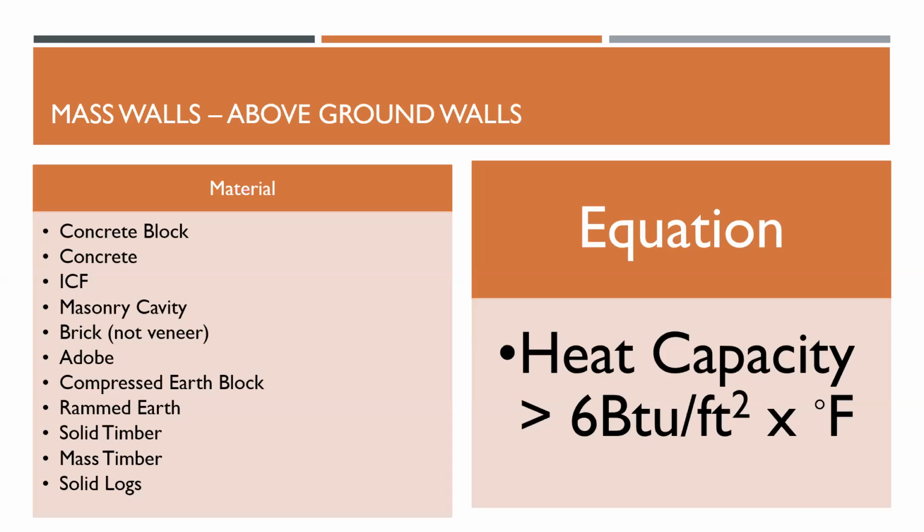Now, if I'm building a 2x6 wall, I think I would want to take credit for the amount of insulation I can get in that wall. R21 is going to be more expensive than R13. I get that, but you can certainly make a better performing wall if you're already doing 2x6.